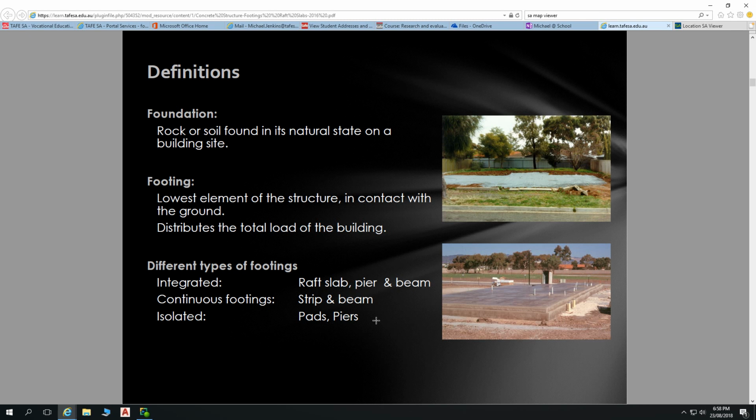In terms of those masonry anchors, whenever we have bracing like this, well, any form of bracing, but this strap bracing here we've got on there, where we've got strap bracing tied down to our bottom plate, we need to have a fixing of that bottom plate straight into the floor slab at that point as well, or within 150 millimetres, because as there's tension put on that, it's trying to pull that bottom plate away from our floor slab.